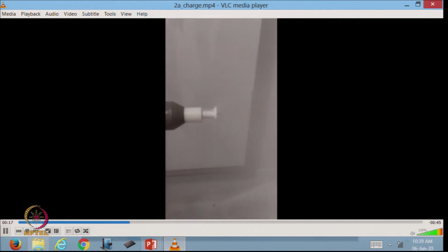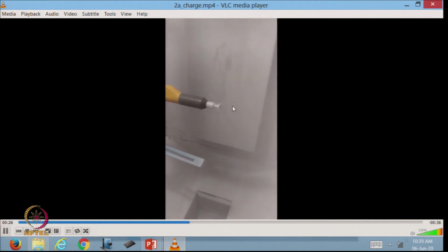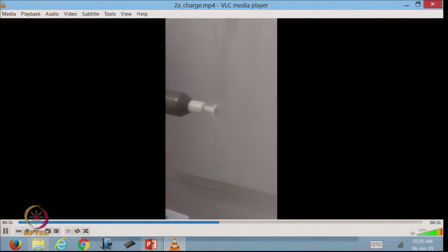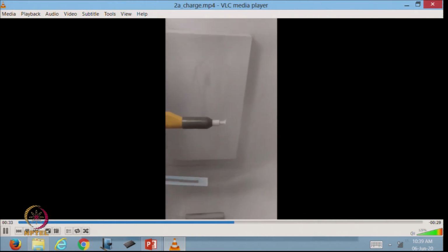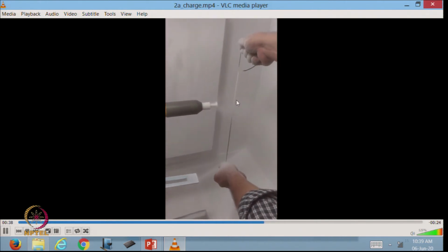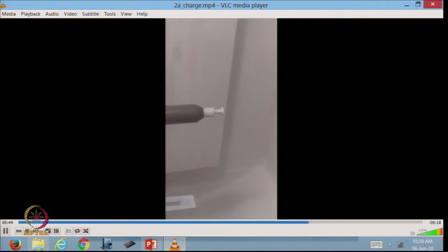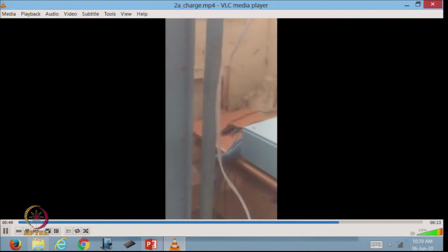This highly charged particle is coming out through this spray gun here, and once the carbon tow is placed, we can see very clearly the coating, it is becoming white, fully coated with the polypropylene powder.